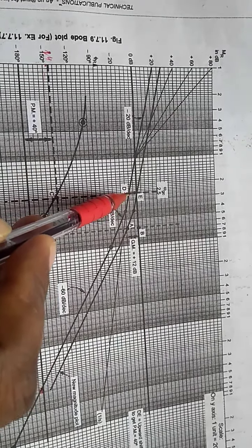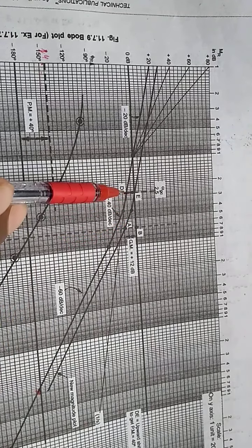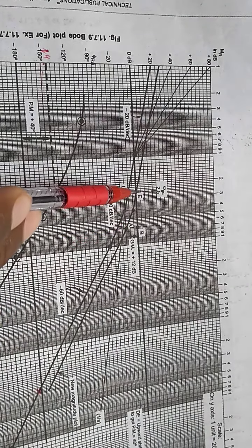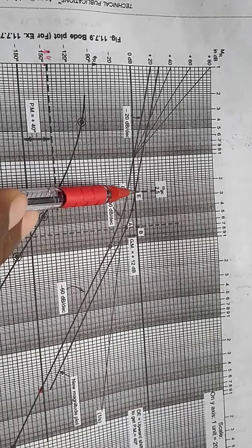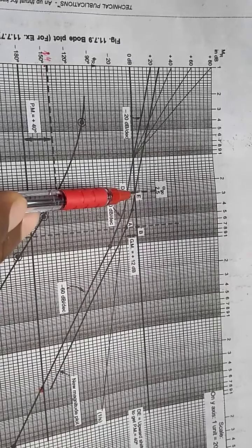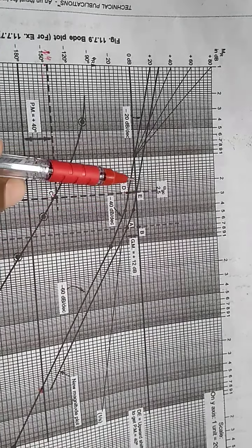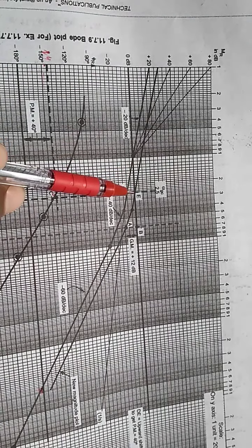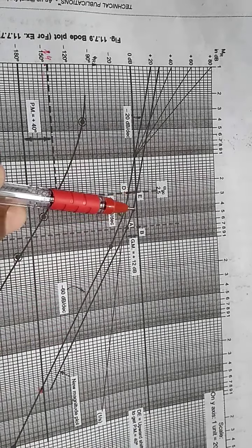Draw the point in the upward direction, because this slope is below the 0 dB. Our objective is to meet the 0 dB line. So we can draw the vertical line towards upward. So this is the meeting point. Then draw the line which is parallel to this old slope. The old slope is the reference. Draw the parallel line for this slope which meets omega equal to 1 at 0 dB. Then the rest of the procedure is the same.